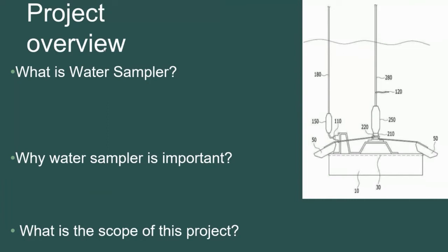What is water sampler? Water sampler are used to collect water sample at specific depth. They can be used in any water body, and the maximum depth is limited to the length of rope you attach to it. It is important to remember that the deeper samples are prone to more drift due to water currents or boat movement. Because of its simple construction, the water sampler is a low-maintenance sampling device.